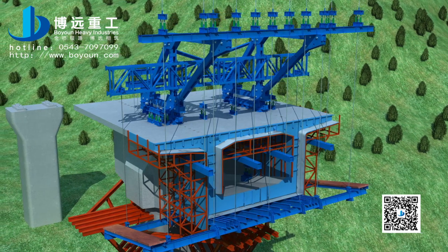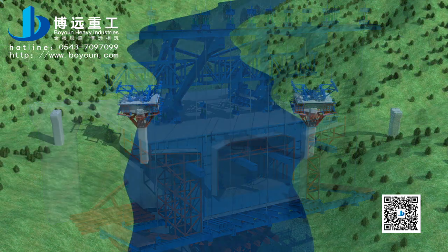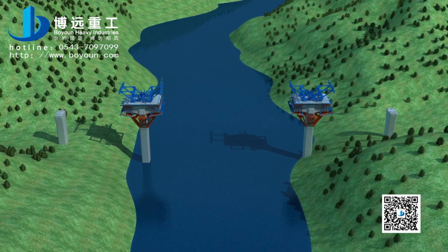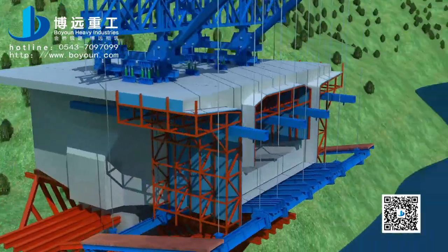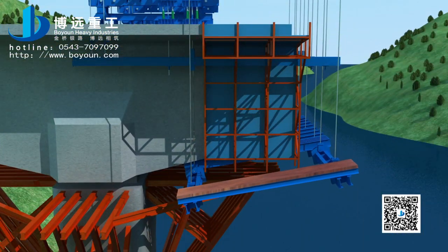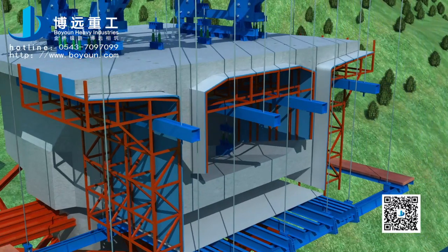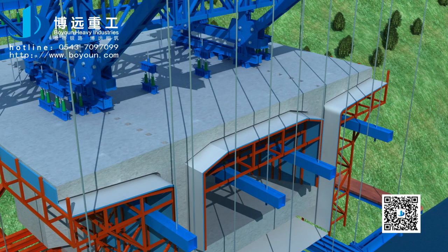After one section casting is complete and concrete strength meets 85% of design strength, follow the principle of synchronization and symmetry to tension the girder body. Ready to move hanging basket forward. Move forming traveler forward. Move bottom support system down 20 to 30 centimeters. And then move nose girder and formwork system down until completely out of girder body. Clean up the top of girder of casted concrete and lay steel pillow.